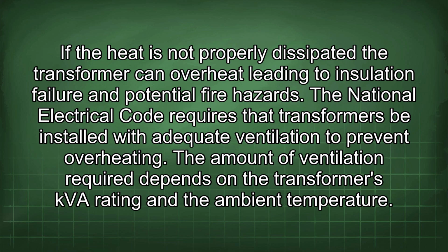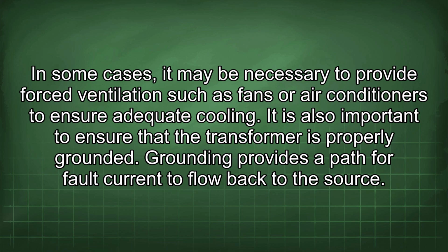The National Electrical Code requires that transformers be installed with adequate ventilation to prevent overheating. The amount of ventilation required depends on the transformer's kVA rating and the ambient temperature. In some cases, it may be necessary to provide forced ventilation such as fans or air conditioners to ensure adequate cooling. It is also important to ensure that the transformer is properly grounded.